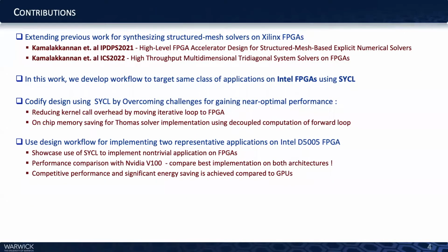The work we did for this paper for IWOCL and SYCL is based on two previous works which we did based on Xilinx FPGAs targeting the structured mesh application class. The first one was published last year at IPDPS 2021 and it developed a generalized workflow for synthesis of near-optimal FPGA designs for structured mesh-based explicit numerical solvers. Basically, stencil applications including larger, more realistic applications with multiple stencil loops. The second work, which will be published in ICS 2022, looks at implicit solvers, specifically multidimensional tridiagonal system solvers for FPGA. Our work for this IWOCL workshop extends these works, investigating the same designs for these application classes using SYCL and developing designs for Intel FPGAs.